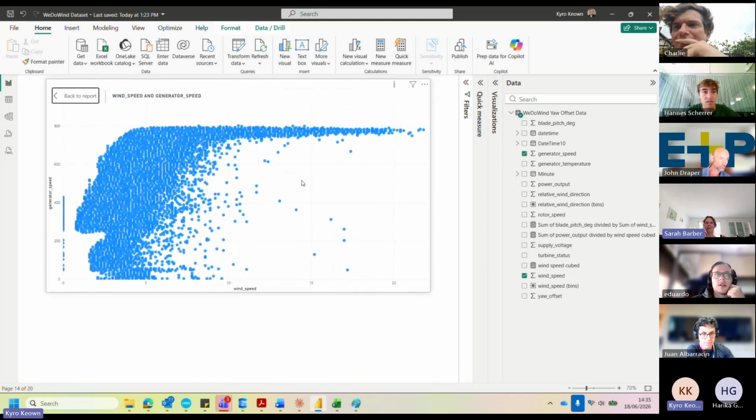This data is making me feel like it might have two, and we didn't realize. Well, as I said, it's across all power ranges and all wind speed ranges. Okay, so maybe not. It's not isolated to a specific time. I really think it's just a sensor issue, because if it was an actual physical phenomenon, it would be reflected on the power curve, which it's not.